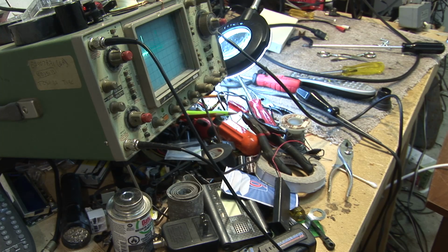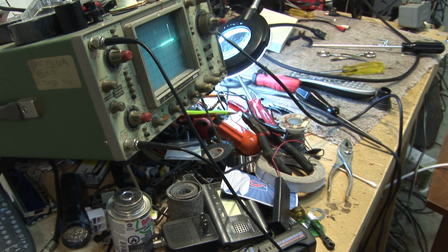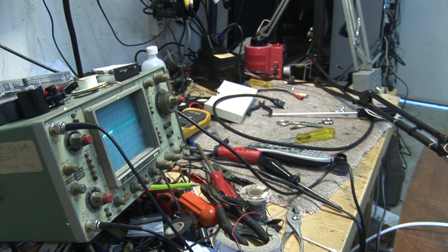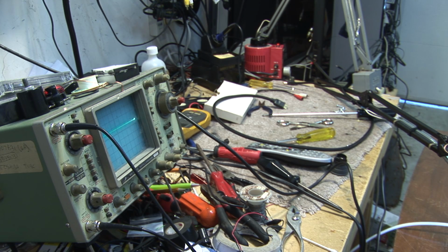Just going to take a few more tests on this circuit and see where our distortion's coming in. Okay, I'm just going to check the bootstrap capacitor here. I'm just going to put my probe on here, and as you can see, we've got some distortion here. That should be a nice clean pulse, but you see it kicking back down on the bottom side there. So we've got some distortion on this little capacitor. It is a small one, as I thought it would be.